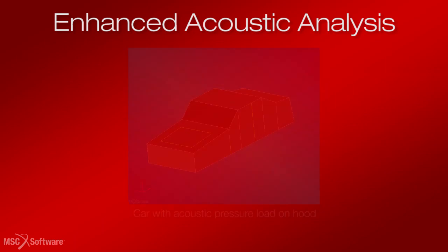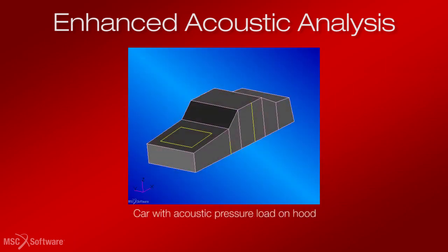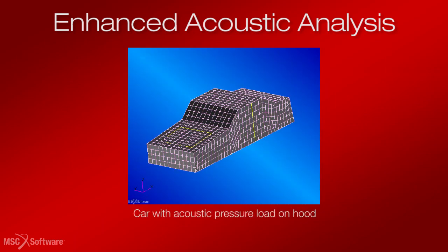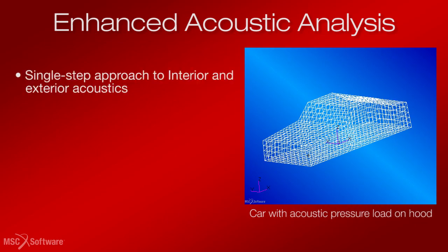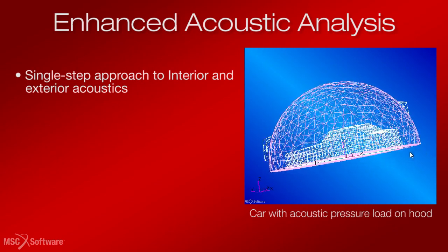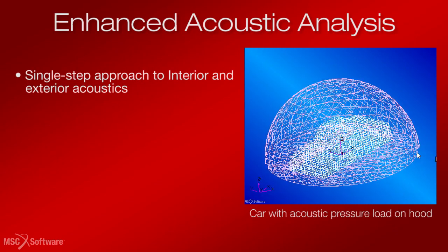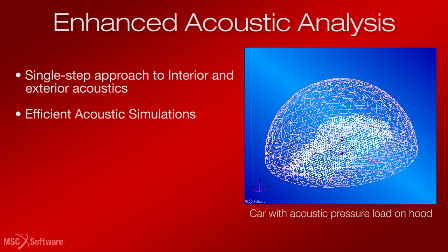Several enhancements are made to MSC Nastran's acoustic analysis capabilities to help users achieve higher efficiency. We now include an efficient single-step approach to the solution of interior or exterior acoustics problems and have implemented a more efficient participation factor analysis exploiting parallelization.